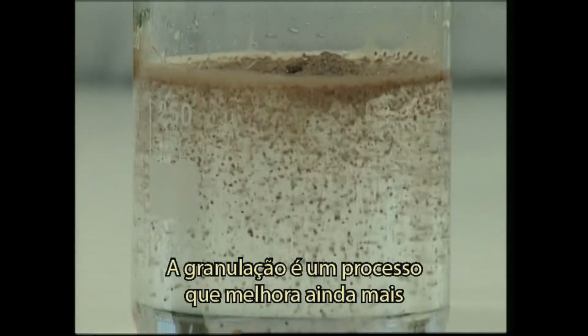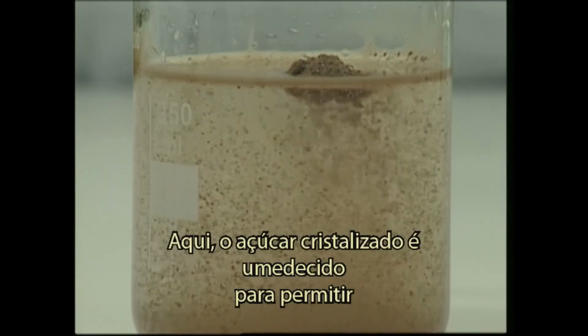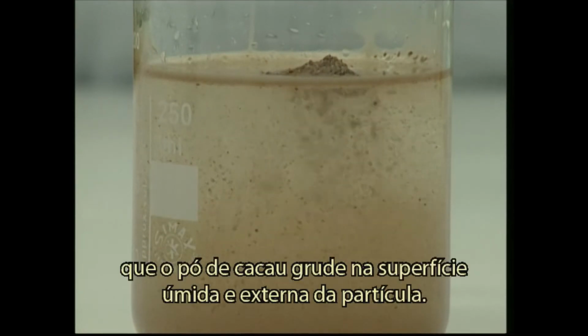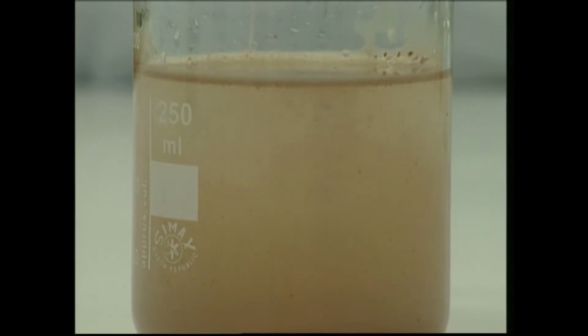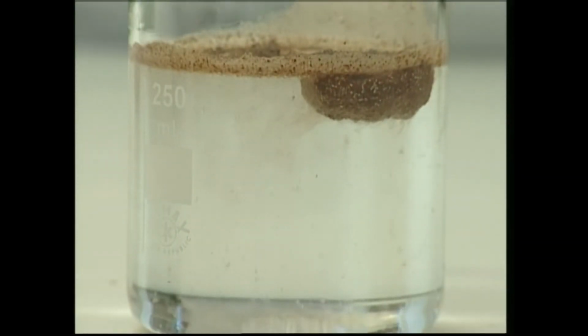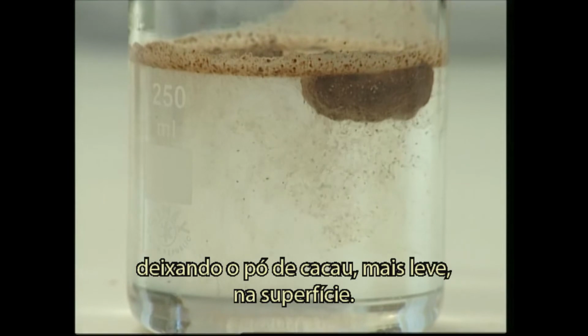Granulation is a process to further improve the instant properties of a product. Here, crystal sugar is wetted to allow cocoa powder to stick on the wet outer surface of the particle. The heavy sugar particles will sink through the wet surface, taking the cocoa powder with it, where a dry mix that is not granulated would show sugar particles sinking into the cold fluid, leaving the lighter cocoa powder behind at the top.